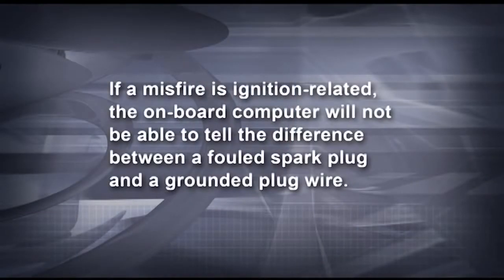If a misfire is ignition related, the onboard computer will not be able to tell the difference between a fouled spark plug and a grounded plug wire. In this case, you'll have to dig deeper to diagnose the misfire. When diagnosing ignition misfires, it's very important to use tools that allow you to see what's actually going on.